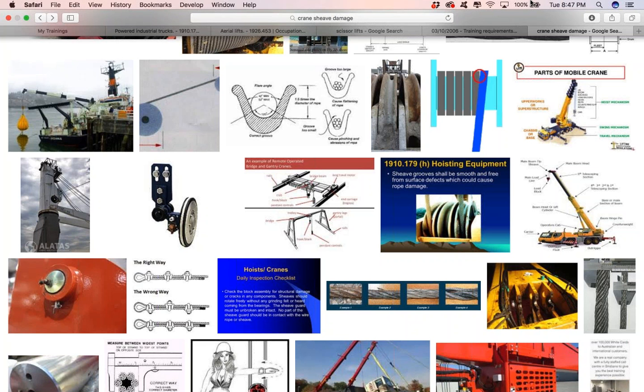Okay, and then there are many ways for the operator and signal person to communicate, right? Like we talked about, radio, signals, okay? And then we have advantages and disadvantages, right? Radio interference. My recommendation is that when equipment is moving, you keep everybody else off the radio. If they're walking all over you, stop operations, determine what you need to do, and at that point, just make sure that you have safe communications. Also, keep any horseplay or clowning off of the radios as well, folks.